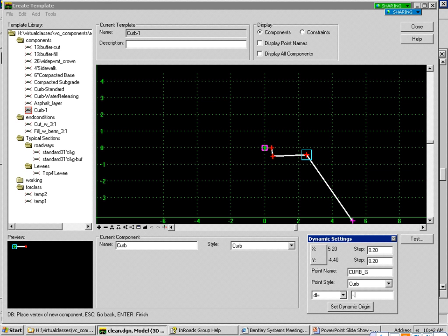So we go minus 0.5. Actually, see, I almost did that wrong. But in fact, I'm going to do it wrong so you can see this. In fact, I'll just put 0.5, comma 2. I just totally did that wrong. I'm going to hit enter. Okay, I made a mistake. Now the beauty of this is, I've got two ways to go. I've got these undos down here if I stop, or I can right-click and say undo last, and I'm right back.